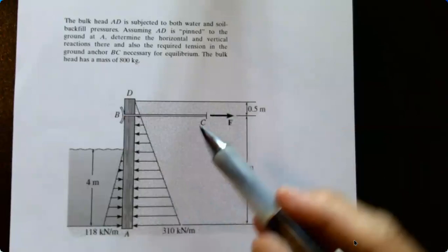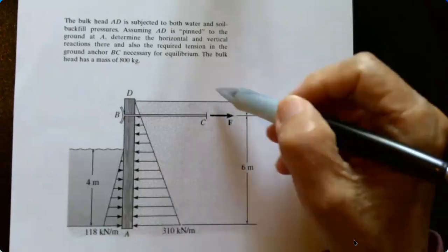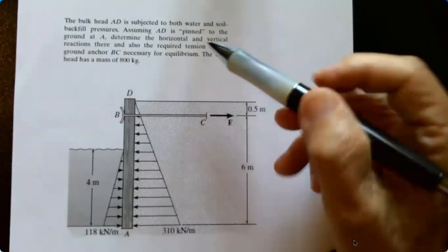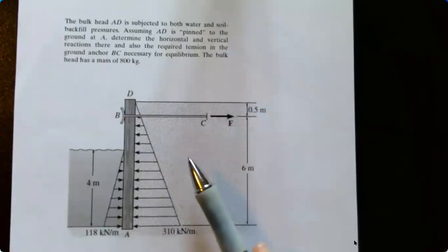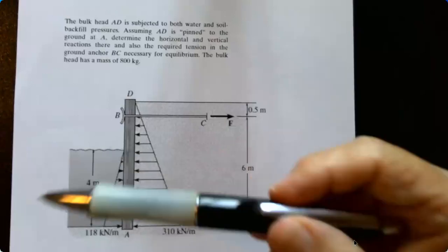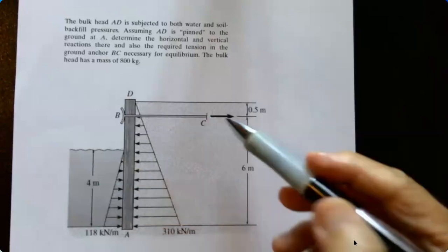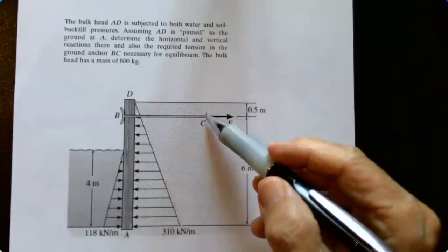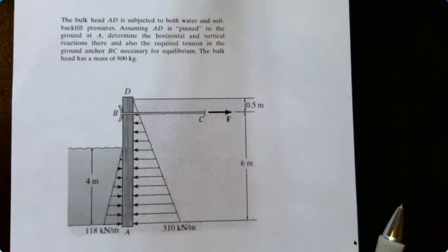Another problem you can have too is if you put parking on top of here, or you build something else on top of the soil at this particular end, it adds increasing weight here and pushes out. So anything we analyze here is just this point in time, but we imagine it's occurring across the length of this bulkhead. And so you can figure out what the spacing would be depending upon the length that you have.